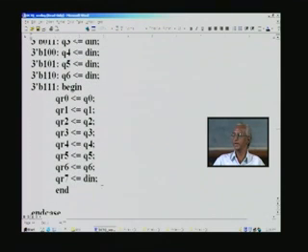This is being assigned here, and instead of putting this for this statement alone, we have done some more things which will take some more registers. The reason is as follows. See, first, once the 7th clock cycle arrives, this has been written, and with the 8th clock cycle the last partial product is written.